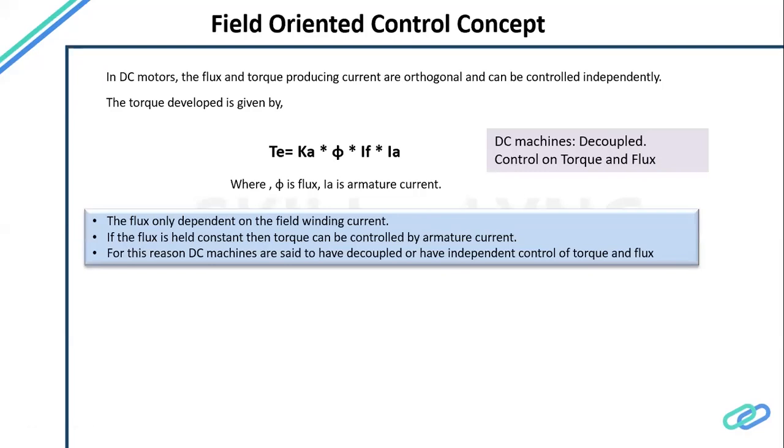If we can decouple this, we can really control whatever we want at a high speed. At high speed, the back EMF is so high that it may be more than VDC, that bus voltage, right? So to do that, we demagnetize the magnet, or we increase the ID. The moment we increase this demagnetizing component of current, the flux starts dropping and the speed starts increasing. Then we can increase the speed, but definitely torque will have a penalty on it, right? So we cannot have constant torque in that region, but power we can maintain because speed is increasing.